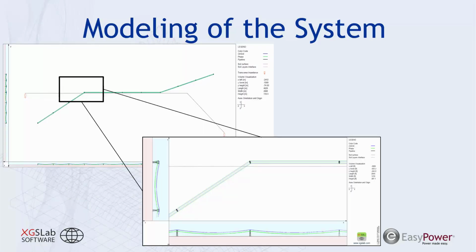And what we end up with is a very complex system with a lot of different pieces from different sources, and it's easiest to evaluate these systems in software such as XGS Lab, where you can import the DXF from your transmission line design model into XGS Lab, and possibly import the pipeline location and geometry from the pipeline design, and co-locate those into your modeled environment. You can incorporate the transmission line structures themselves and the shield wires, and account for how much induction occurs on the shield wires and how that affects your overall magnetic fields at your pipeline. And this is able to account for very complex systems that have multiple transmission lines, multiple recipients, and multiple operation scenarios to evaluate.